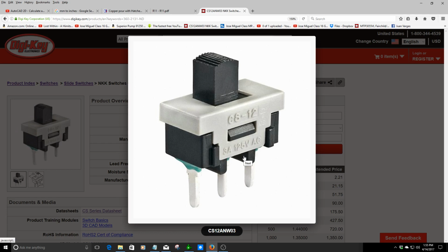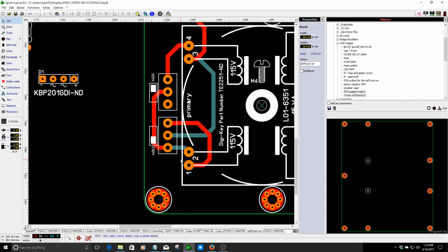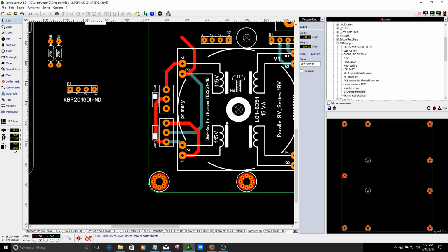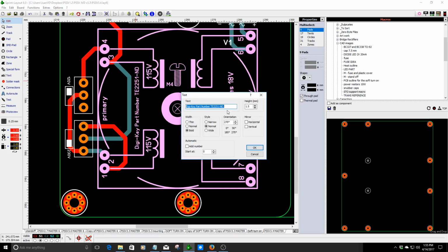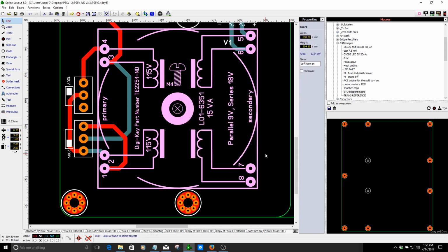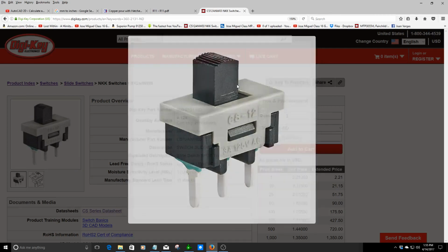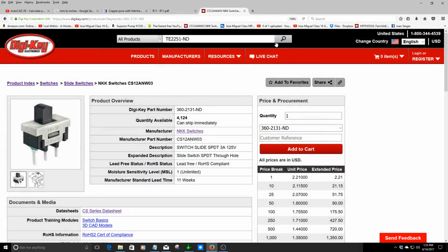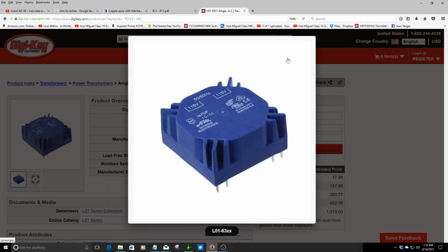And this should be just fine because this is 3 amps, 125 volt AC. So I don't think the transformer is going to draw a lot of current. I was reading that this particular transformer, for the 230 volts, uses a 100 milliamps fuse. So I was really curious about that. So I need to place a fuse for this small transformer.